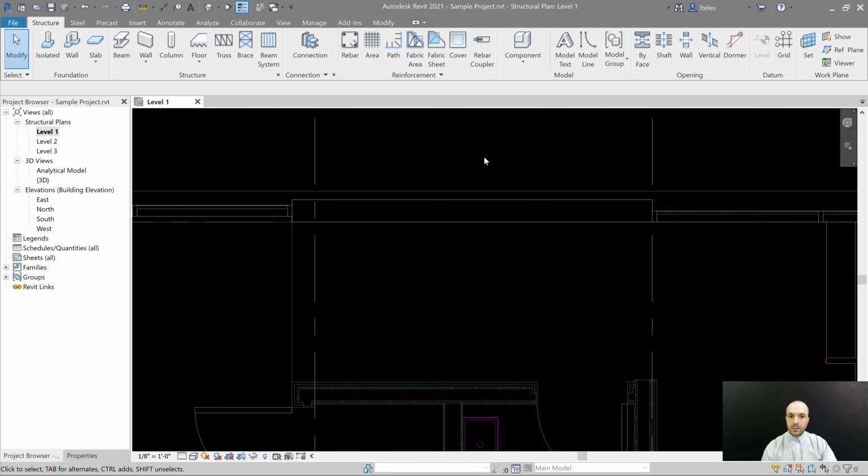Now I'm going to draw a vertical line here so I can use that line as a reference to use my extending tools. So annotate, and now we'll go to detail line, and I'll just draw a line just like that. Escape twice. And now on your keyboard type in TS for trim single, also known as extend single. Select your destination, select the element you want to extend, and hit OK, and hit escape twice. Okay, so we have 3 walls in here so far.